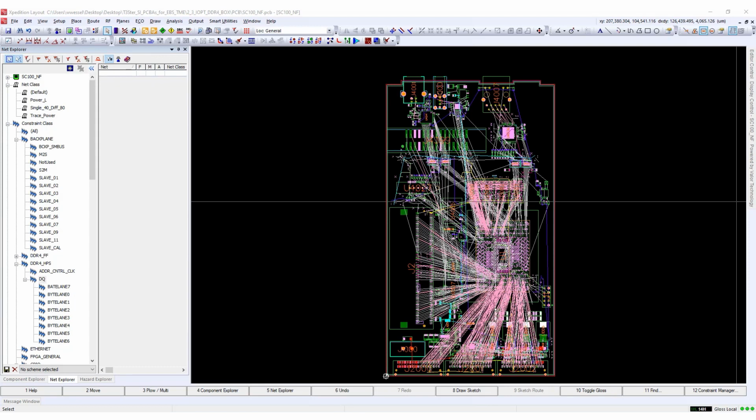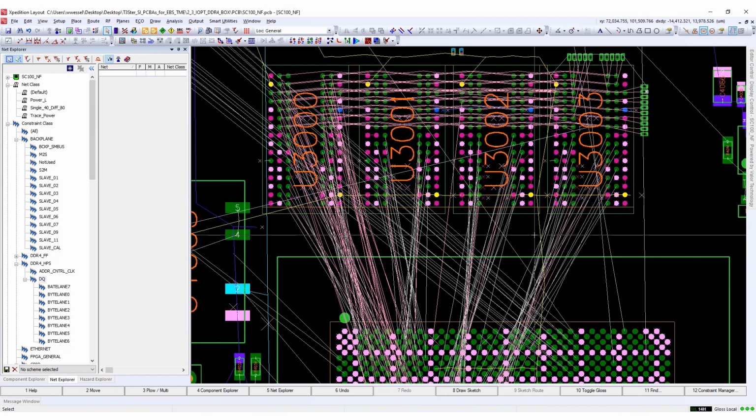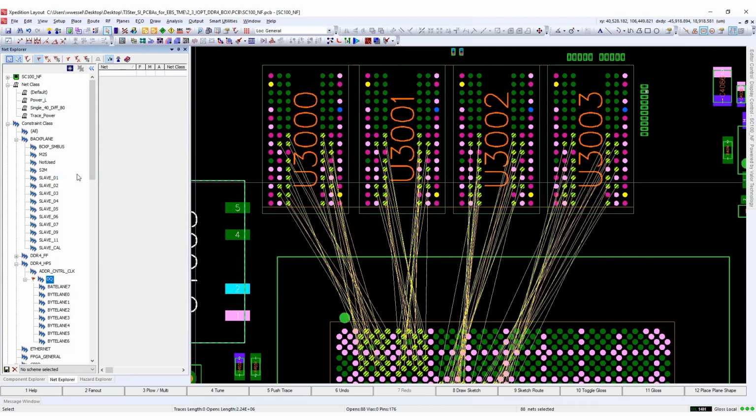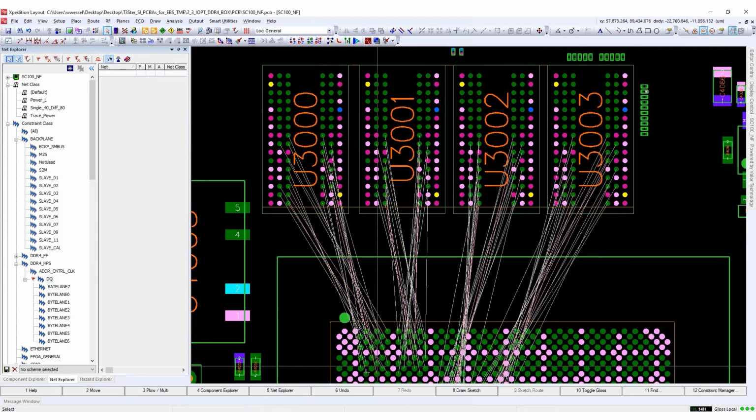Based on the component placement, I want to pre-optimize the FPGA pin assignment to reduce the breakout and fanout effort. These steps help us to identify channels much easier and allow us to make good design decisions about routing layers and sorting of signals. Netline filtering helps me to define a strategy upfront, and I can set the focus on critical nets like the DDR4 data and strobe signals. In addition to that, it is easier for me to review changes in the pin assignments later.